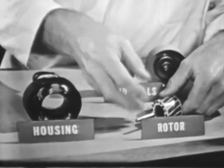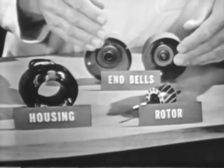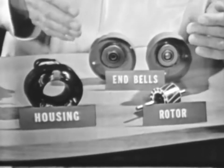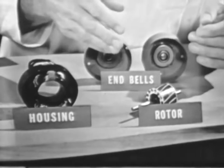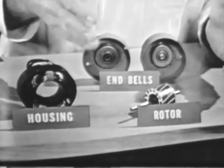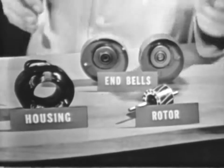Simplicity of construction, which of course leads to lower cost of manufacture and a very rugged design, makes the induction motor a very popular one. There are no wires on the rotor to burn out, no brushes to wear, no commutator to get scratched or pitted. All in all, a pretty good motor. Of course, it's not perfect for every application. It does have certain limitations. But even so, it's used quite extensively.